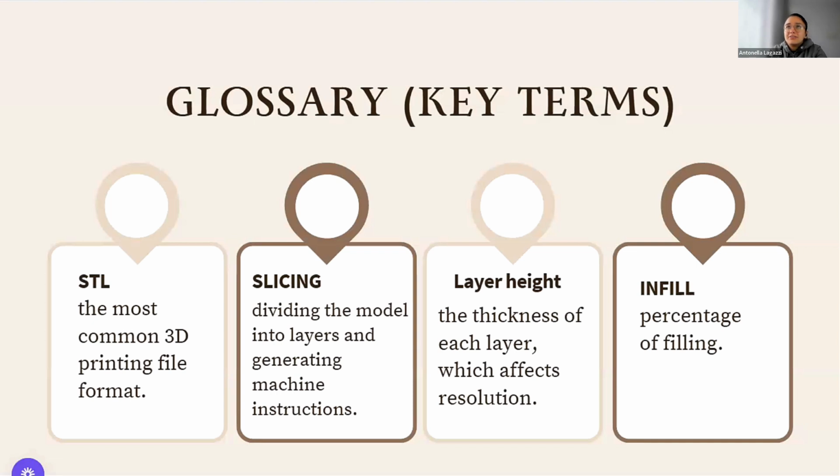And the majority of the time you have to make several tests to discover the best configuration of layer height, infill, and other parameters that are really important to achieve a correct mechanical, and maybe with the material selection, chemical behavior of your 3D printed part.